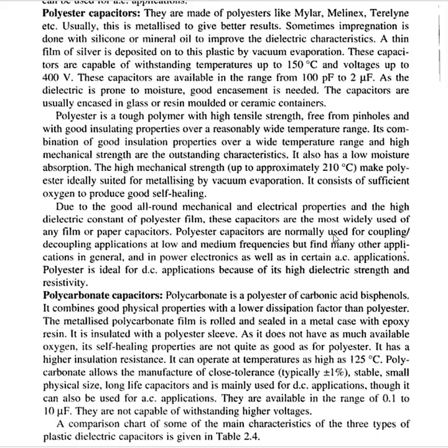Polyester capacitors are normally used for coupling, decoupling applications at low and medium frequencies, but find many other applications in general and in power electronics, as well as in certain AC applications. Polyester is ideal for DC application because of its high dielectric strength and resistivity.